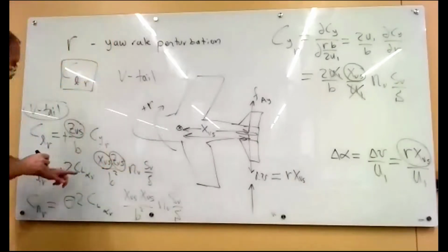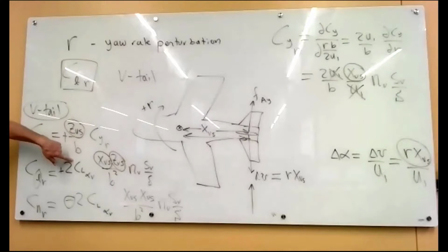I still don't have that. Change in angle of attack times the lift curve slope times Q bar S, and then you're done. There's the force. And then if you're doing a rolling or yawing moment, you find the appropriate moment arm to multiply the force by. So really, this is just statics. Force times distance for moments, and force is just force. What complicates it is all of the forces are generated aerodynamically, so you have to figure out the aero model for the force.